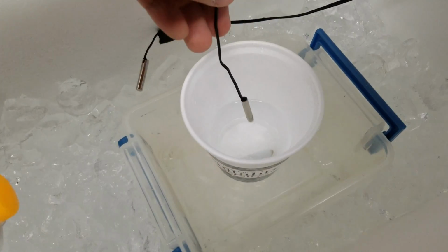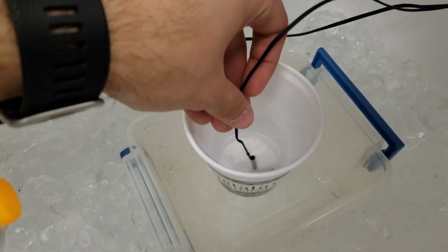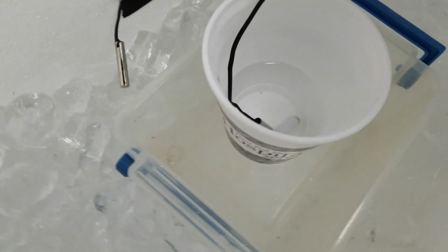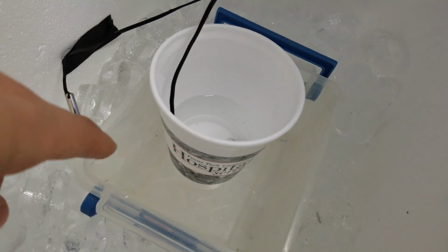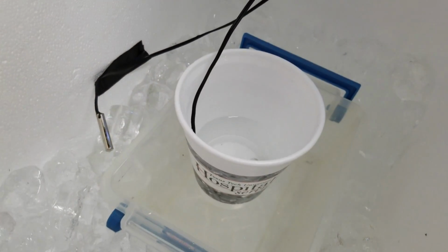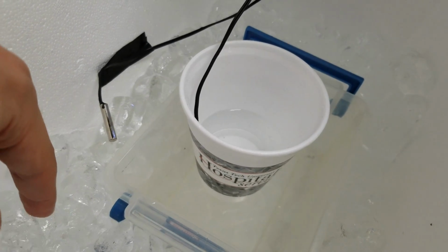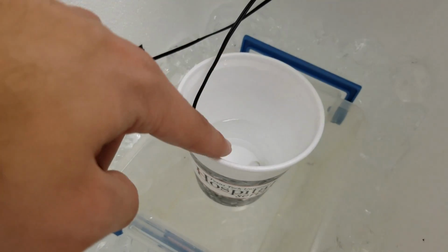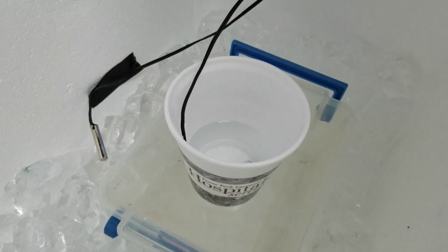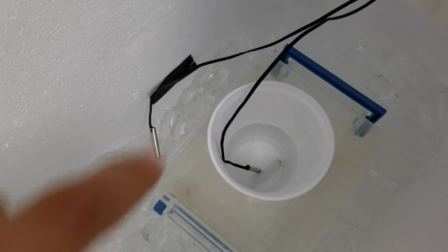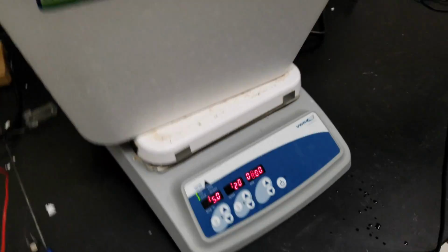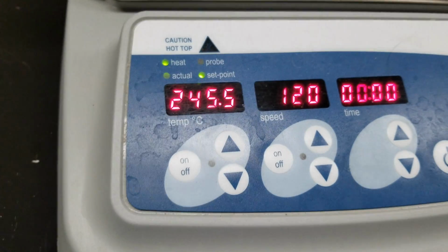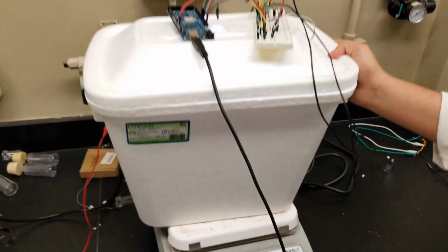This is the temperature sensor that is measuring the temperature of the water in the cup. It's our response variable, or response temperature sensor. The cup is sitting inside of a plastic container which keeps the ice off of the walls of the cup to better simulate just a cold environment rather than ice surrounding the cup as if it was in a cooler. Inside there we have the spin vane, which is also another parameter which we control through a constant RPM.